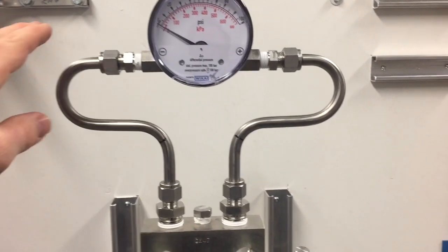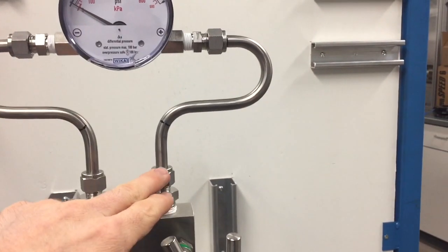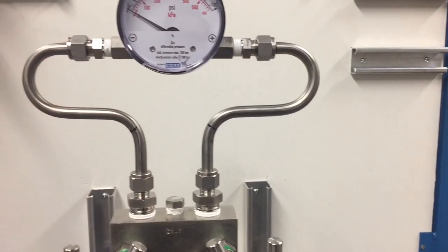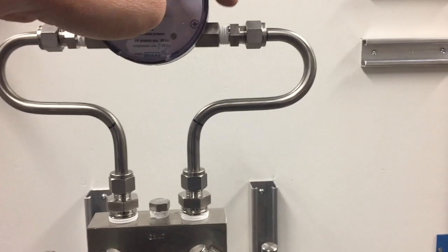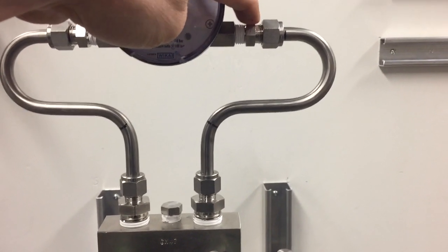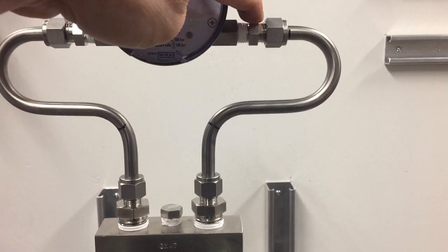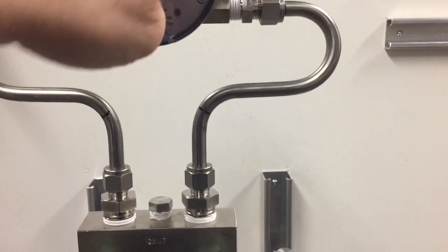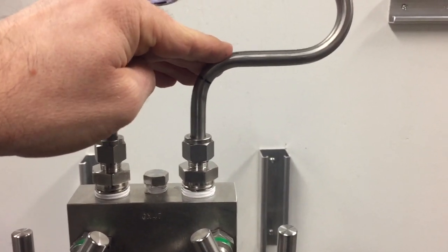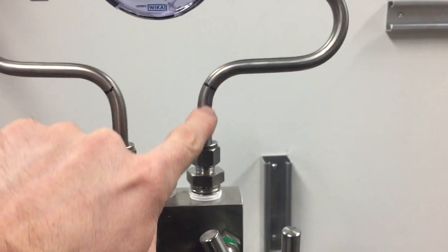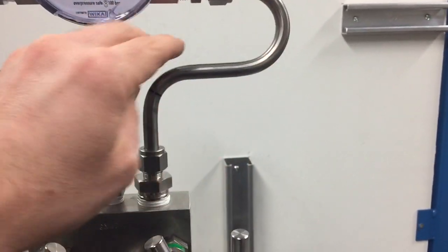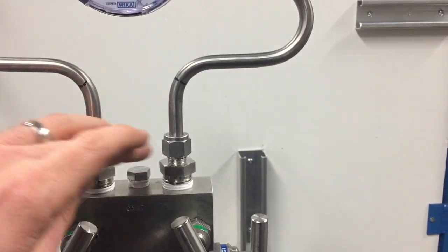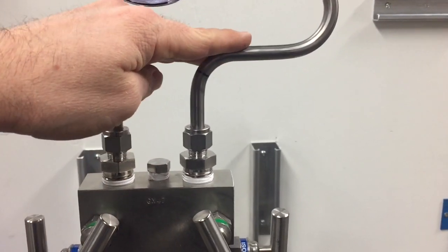I would maybe suggest you take this apart and set each of the tubing fittings individually, just because if you have a look here, the one tubing is slightly shorter, right? And we want to make sure that this tubing here is all the way down. It could have to do with the spring back on our bends. After we bend the tubing, it might spring back slightly. Could be that I've slightly cut one of these shorter than the other.